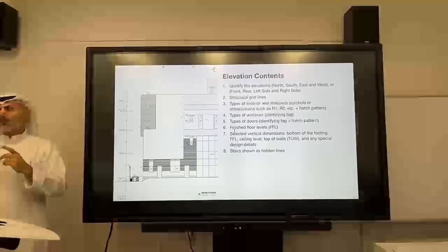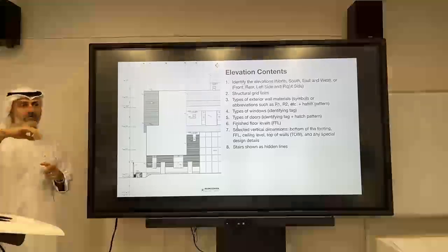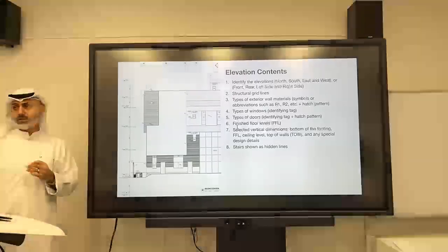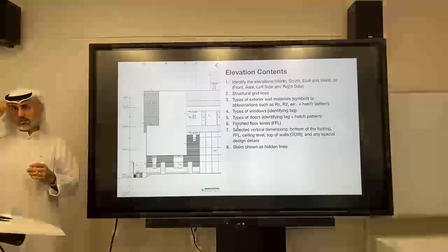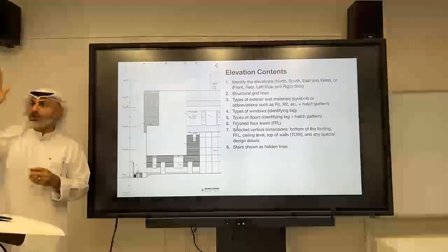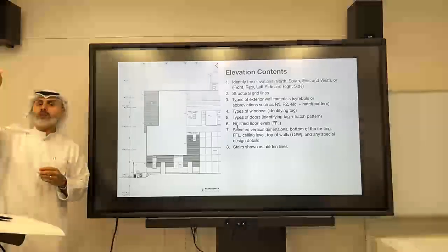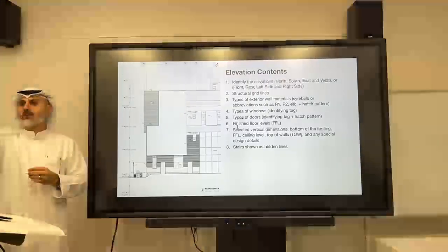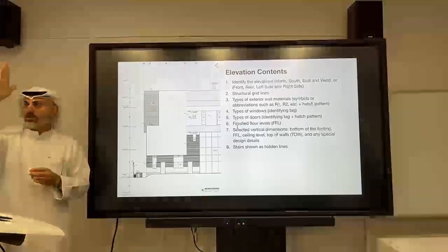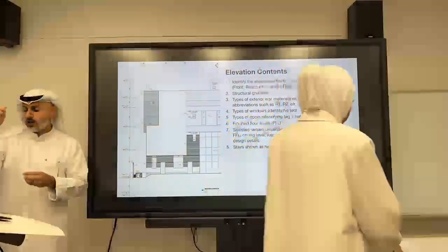Actually, by the way, just going back a bit, the north arrow, it's rotated how many degrees? 30, not 30 something. So check your north arrow in your site plan and your plans. Make sure it's rotated when it's vertical. Just rotate it 30 degrees. Some of you have more. Generally, most of you have more, maybe 40 or 35. So just go back to 0 and rotate to 30 degrees.